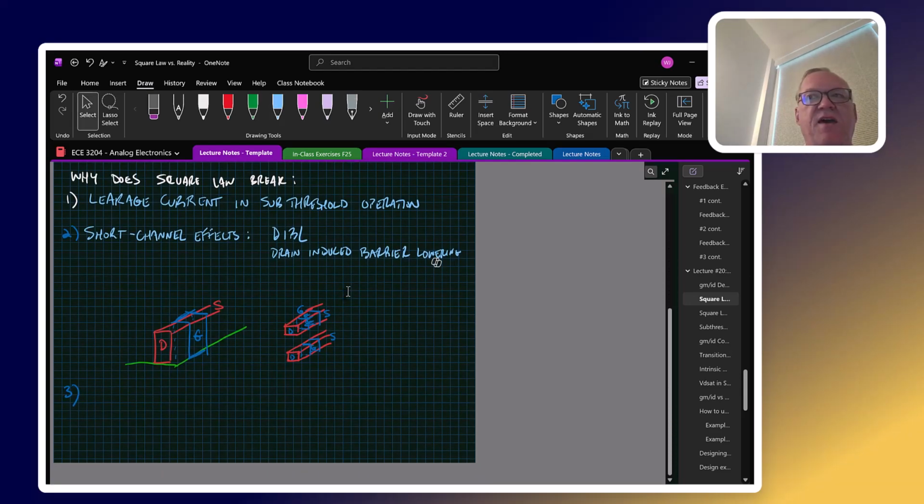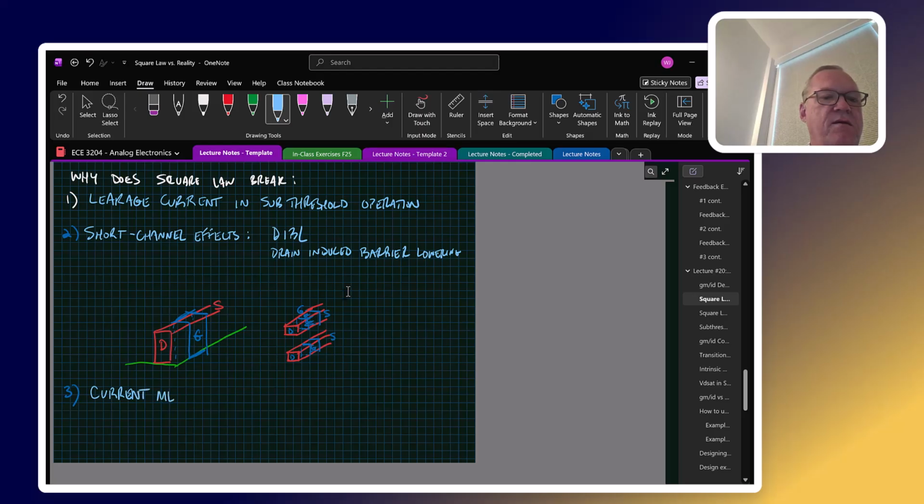Fundamentally, what's happening at really low voltages and in the subthreshold region, though, is that the current mechanism in a MOSFET is supposed to be dominated by drift, but what we see is that the current mechanism is changing from a drift mechanism to a diffusion mechanism.